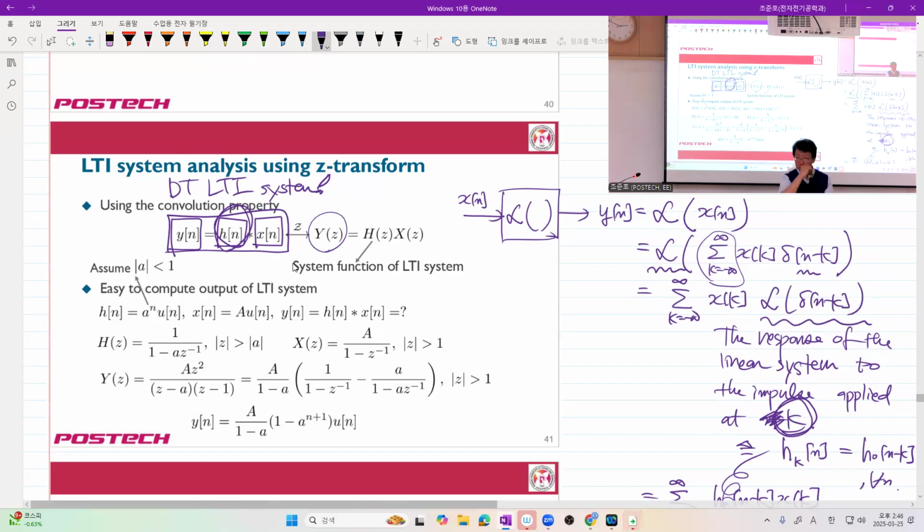The discrete Fourier transform allows a fast computation algorithm called the fast Fourier transform. By the way, the discrete Fourier transform is the name of some transformation. And the fast Fourier transform is what? The name of an algorithm that computes the DFT very fast. What does that mean, very fast? With less computation. What does that mean by less computation? A smaller number of complex multiplications and complex additions. Right? Simply put.